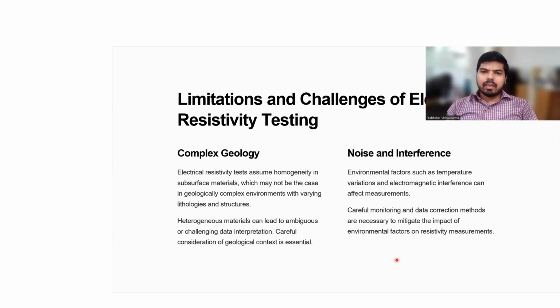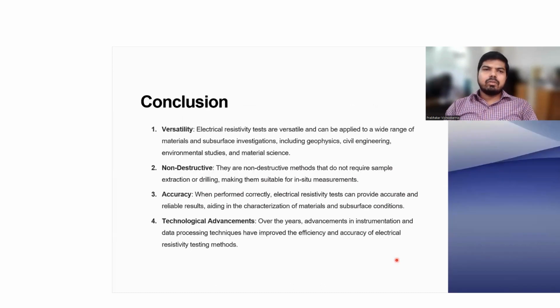So careful consideration of geological context is sometimes required. Then noise and interpretation: environmental factors such as temperature variation and electromagnetic interference should be considered while performing the electrical resistivity test.